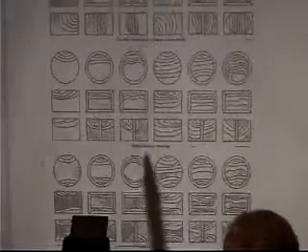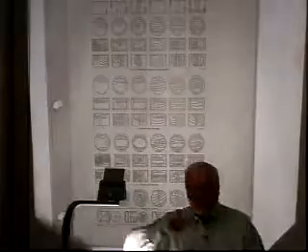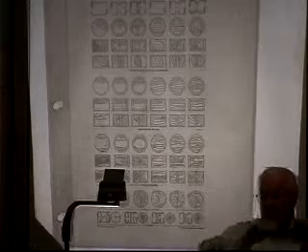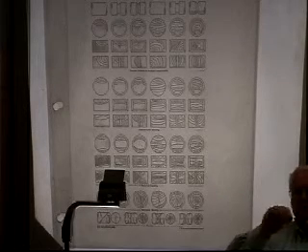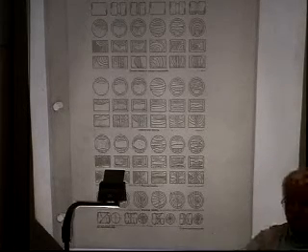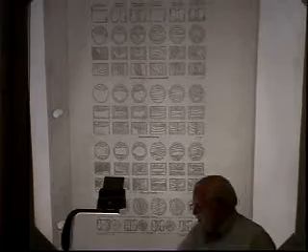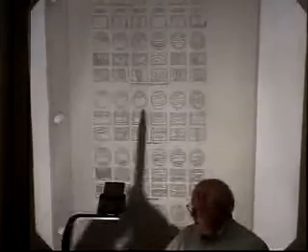If it's on both sides, then it's reverse bending. If it's a fatigue crack and it's only on one side, then you say, oh, well, it could either be bending or it could be tension. So it could be either a tensile stress from bending or it could be a tensile stress from pulling, so far as that goes. However, you can then look at other features of the thing.